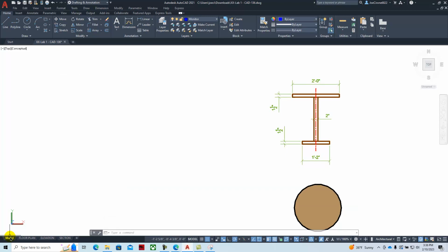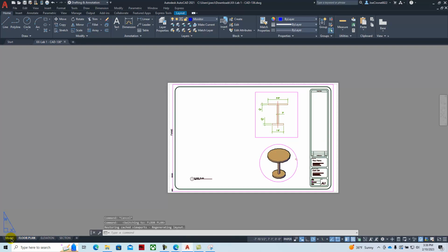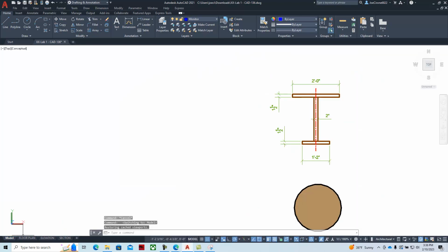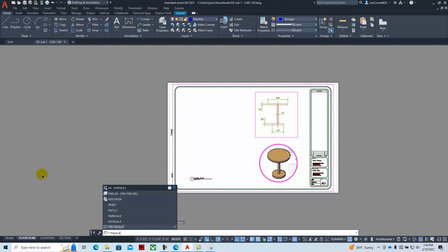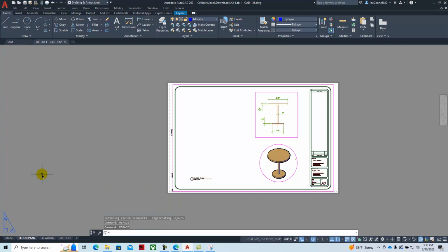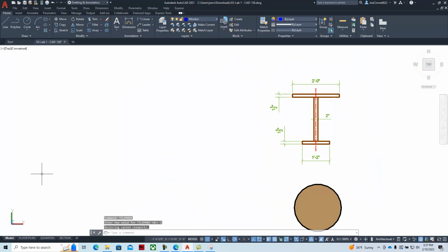We're here in model space. Remember, layout mode is with these tabs down here at the bottom. You can get back and forth between them by saying M space to get into the viewports, P space to get out of the viewports, or tile mode and changing your tile mode variable from 0 to 1 and vice versa.